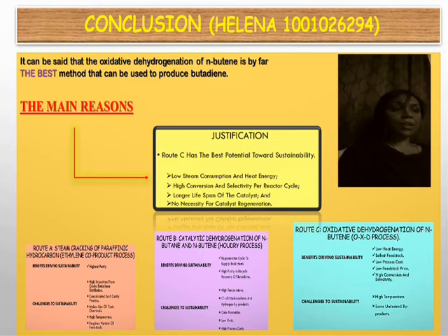With that being said, ODH, or oxidative dehydrogenation of N-butene, could reduce costs and save energy. Capital and operational efficiencies are gained by eliminating shutdowns due to decoking processes, and also because they could conduct fewer maintenance operations because of the lack of premature shutdowns due to decoking process.